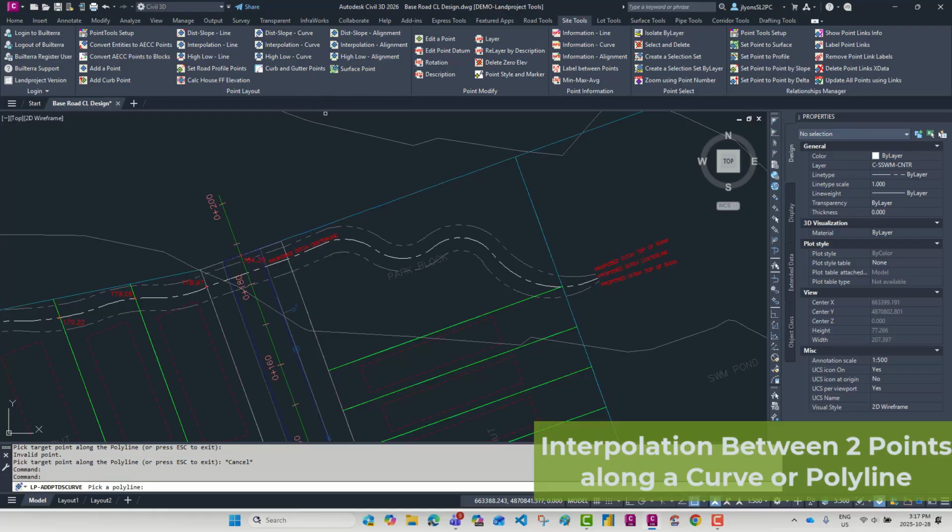In Create mode, the tool uses the curve distance from the start point to the selected location and applies the calculated grade to determine the elevation of the new point. In Edit mode, the same grade is applied to update the elevation of an existing grading point. The endpoint's elevation is recalculated using the curved path distance, ensuring the grading relationship remains consistent along the geometry. By measuring distance along the curve instead of in a straight line, this tool produces more accurate results for grading features that follow curve layouts.